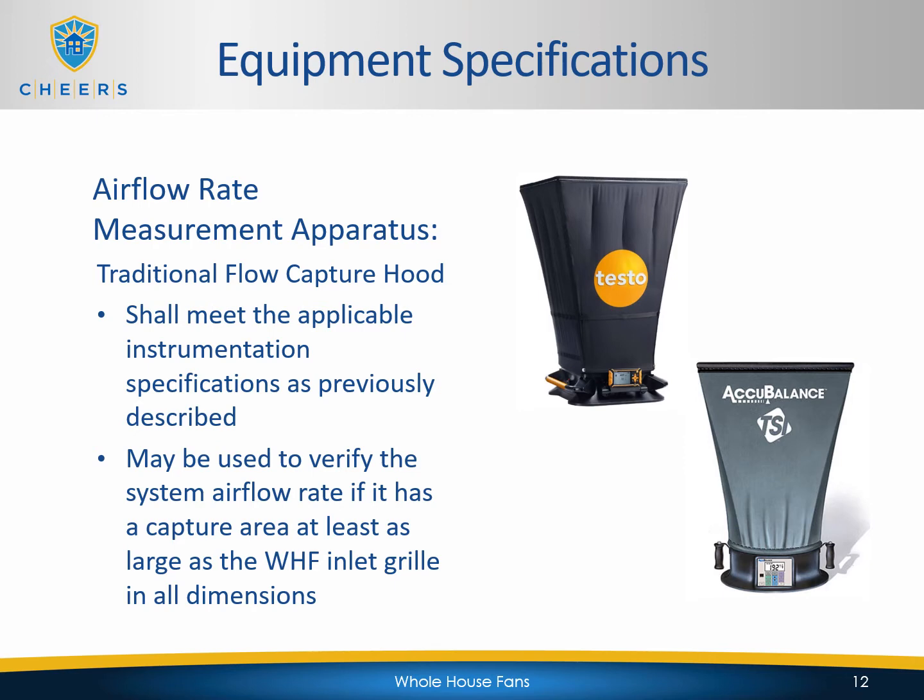Both of them work, both of them have their pros and cons, and both of them need to be large enough. They do sell different size adapters for the top of that hood for different size grills. So if you're going to use this, you need to make sure that the hood on the device is large enough to cover the entire inlet grill of that whole house fan, and that goes for both the traditional as well as the powered flow capture hood. So either one can be used, as long as that hood is large enough to cover that grill and the hood is rated for the amount of CFM that fan is designed to move.